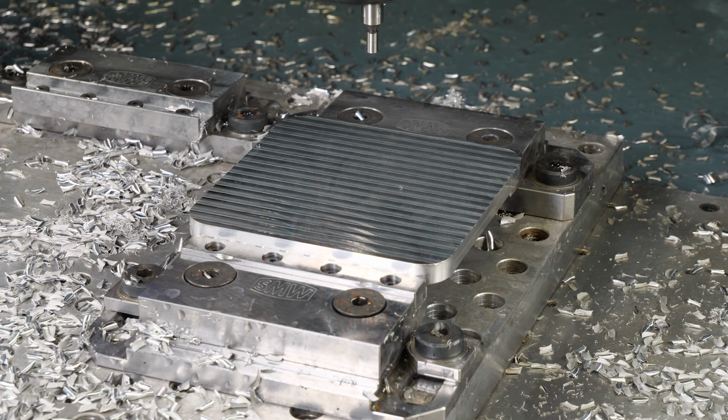And that's when you know, oh, I've just gone past the edge of my part. So then you back it off, maybe a thou or two, until it's back to rotating almost perfectly. You raise it up, and then just like with the end mill, we come over half our tool diameter, which in the edge finder would be about 100 thou, and then we set our X0, our Y0. We can zero our part without having to cut into it.